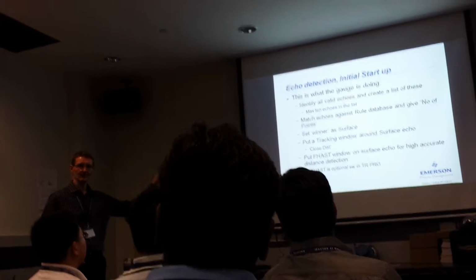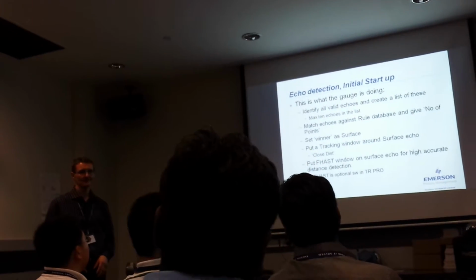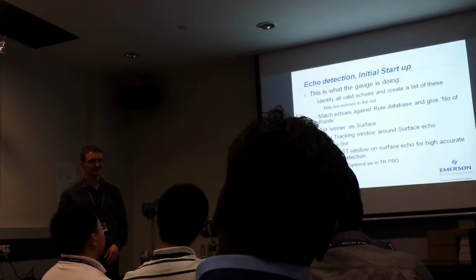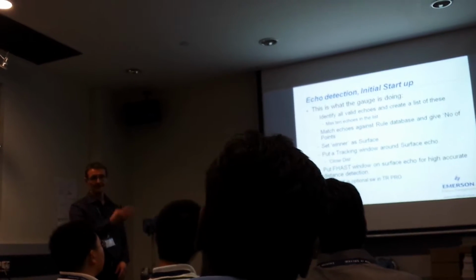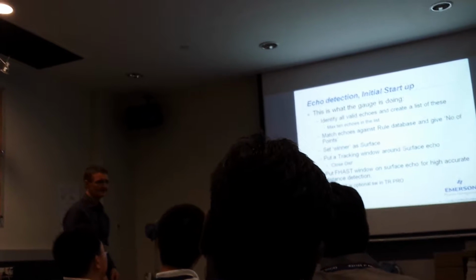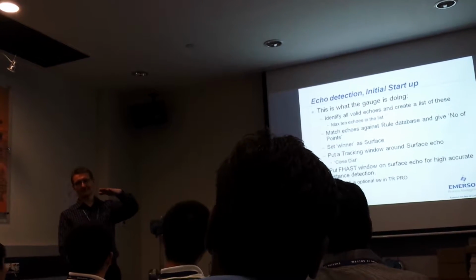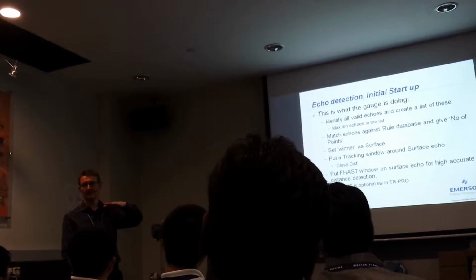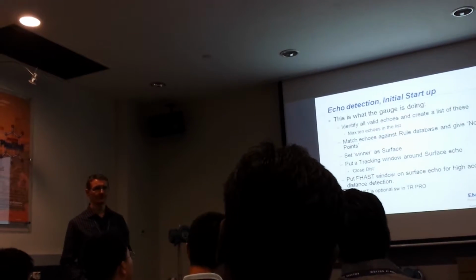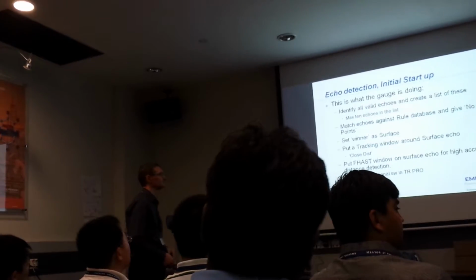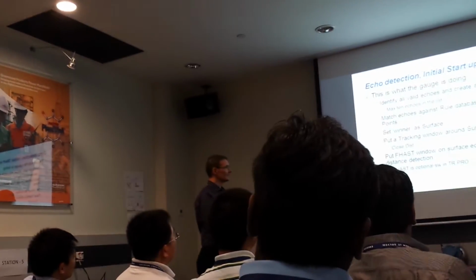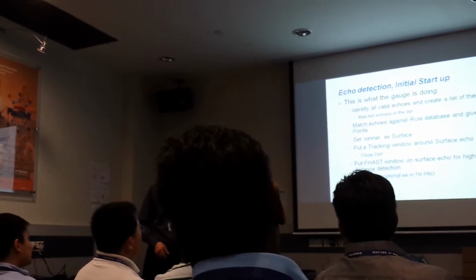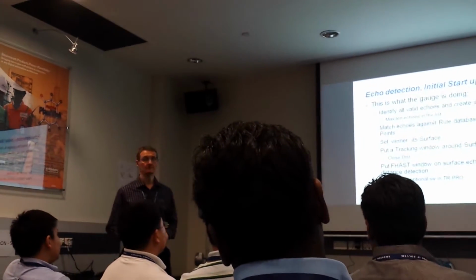Do you remember the value? 800 millimeters. It can be, if you set it 800. Default value is half meter, 500 millimeters. That is the default value. Then, of course, we have the fast filter to get higher accuracy if the level is very stable.